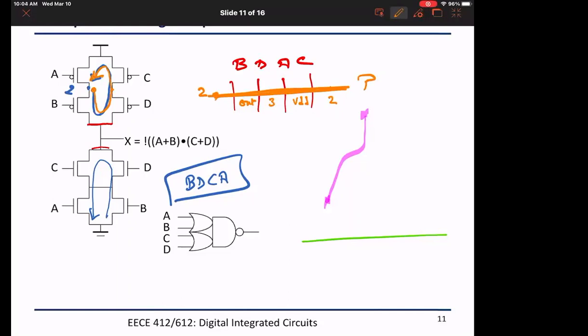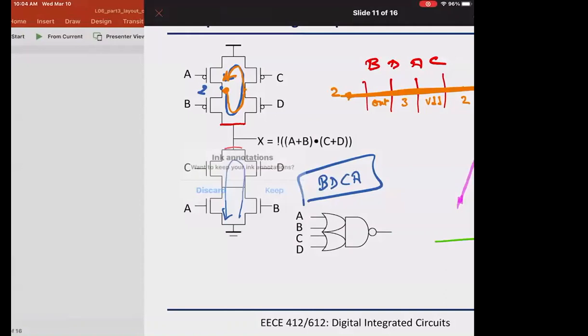So you can envision that I took this line, I held my hands on this end and on this end, and I flattened it. So if the Euler path is simple, and it is one cycle, then it would be easy for me to guess, yes, here I am going to have the output one diffusion in P, have one diffusion in P, oh no, 2 has 2 diffusions in P. Maybe for this scenario, it would have been better if we